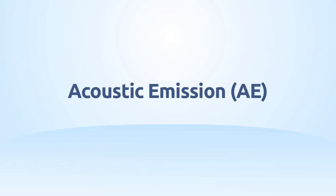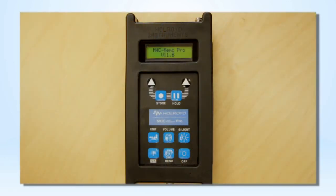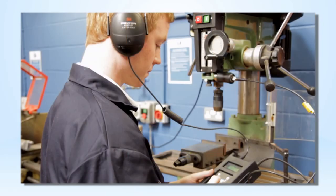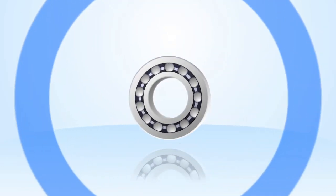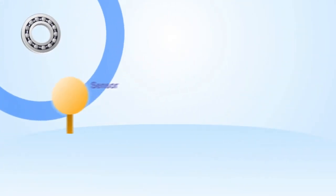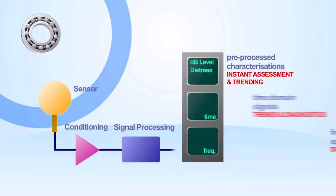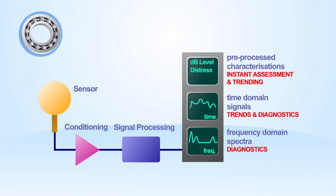Acoustic emission, or AE for short, is a fast and effective method of determining the health of rotating elements. The MHC Memo Pro utilizes AE to listen for friction and impacts caused by poor lubrication or bearing damage. Sound is generated by bearings, and this propagates through the structure of the machine. Using a sensor to pick up the signal, you can detect this noise, and using signal processing, determine the condition of the bearing. Kittiwake Holroyd's acoustic emission technology has been used on all types of rotating equipment for over 20 years.